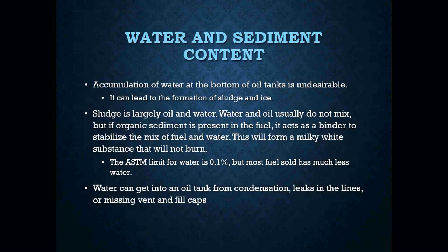Okay, so water and sediment content is the accumulation of water at the bottom of a tank, and obviously that is going to be undesirable. We want to keep water to a minimum when it comes to your oil tanks. It can lead to the formation of sludge and ice. Sludge is largely oil and water. However, water and oil usually do not mix. But if we add organic sediments to that fuel, it's going to act as a binder to stabilize that mix of fuel and water. This will form a milky white substance that will not burn, and that milky white substance is going to settle at the very bottom of the tank.